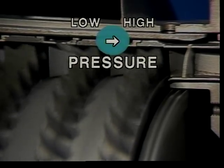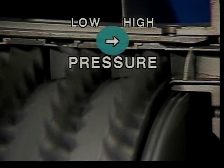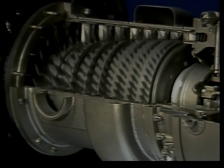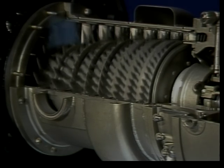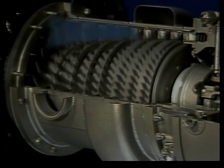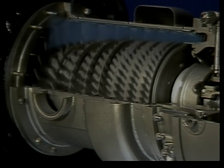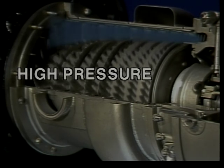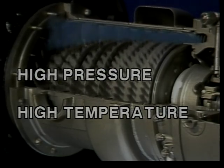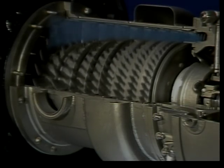A very small pressure at the first stage quickly becomes a very high pressure at the last stage. Remember that the air path decreases in size along the compressor's length. This permits the compressor stages to maintain the pressure passed along from the previous stages. Now, with an increase in pressure goes a similar increase in temperature. So the air leaving the compressor has gained high pressure and a high temperature. This is done by alternately speeding up and slowing down the air in an ever-decreasing air pathway.